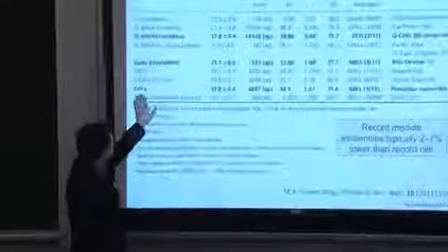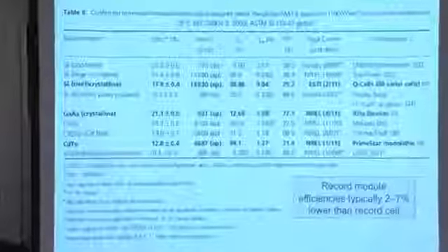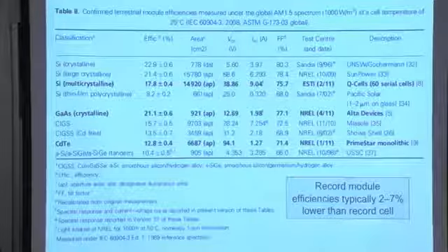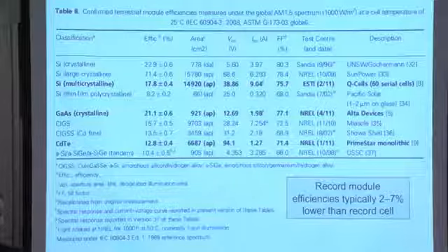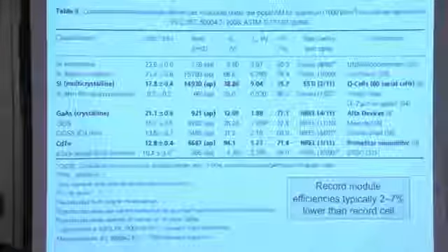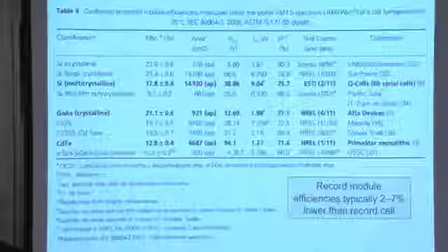That's where the majority of that comes from for, say, crystalline silicon or discrete monolithic wafers. But how about for some of these thin film devices? They're deposited using these large chemical vapor deposition reactors, for example, or PVD reactors. And you deposit a uniform thin film over a large area, you use lasers to cut little trenches in the films and discretize the devices that way. So how come there are differences between record cell and record module for a thin film?